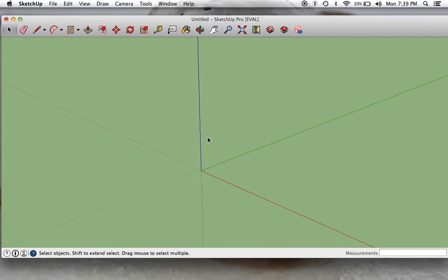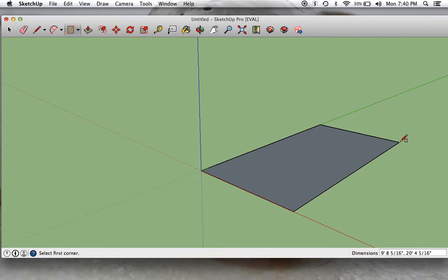Some of the basic tools that you'll need to work with on this toolbar up here are the rectangle tool. So if you click on this, you'll be able to create rectangles. And if you come down here and start at that point of origin, you'll notice that you can create your size. Notice what's happening in the lower right part of my screen, the size dimensions. So make sure you're aware of that and you aren't creating something that's hundreds of feet long. So you should be in the 10 to 20 feet long. And when you unclick, it locks it in.